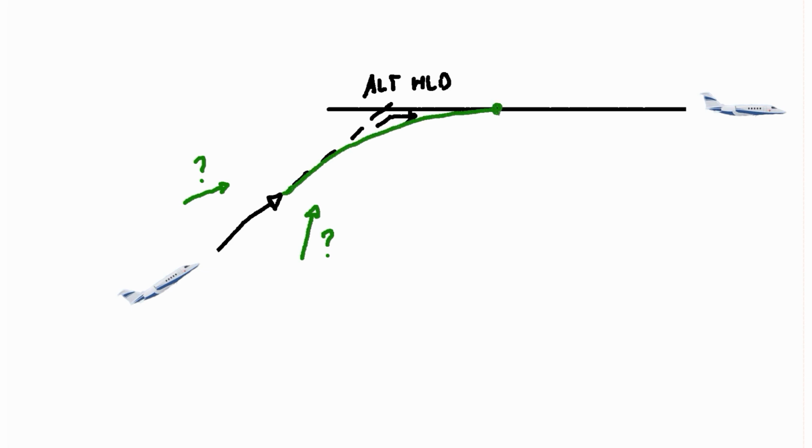And once the circle connects the current rate of climb with the altitude, the altitude acquire function, or the altitude star function, engages. So you see that here in this case, the altitude acquire will engage at this altitude, which could be, I don't know, 400 feet before, okay?